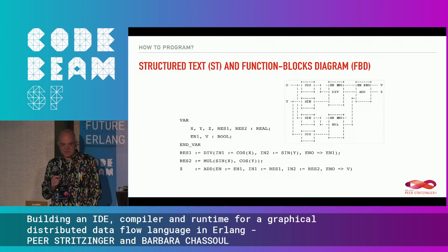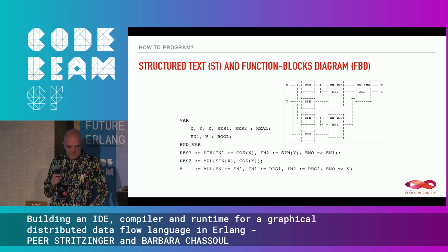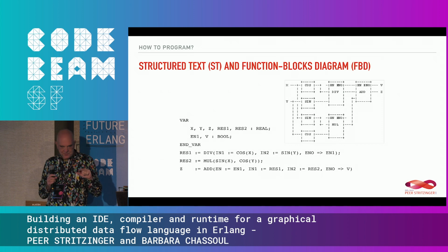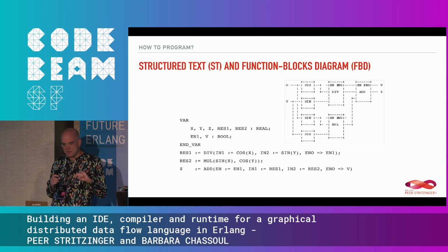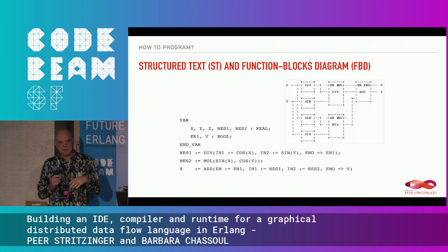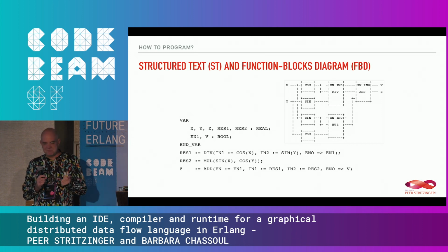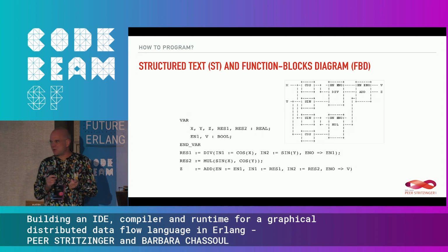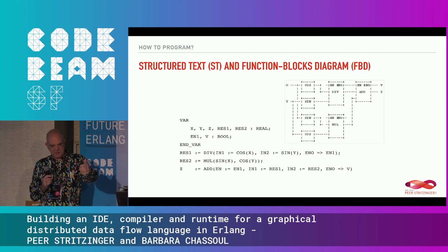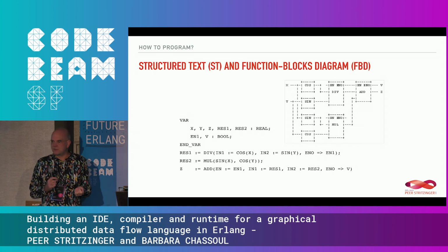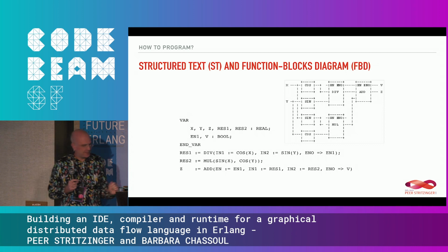And there's also a representation of the thing, and I think I put the same program that's in structured text down there as function blocks. So those little boxes are kind of like functions. So it's almost functional reactive programming. It always has a data flow approach, even if you write it in structured text. By this constant looping thing, it is then synchronous data flow, basically. Because in every loop, you progress your data flow once further.